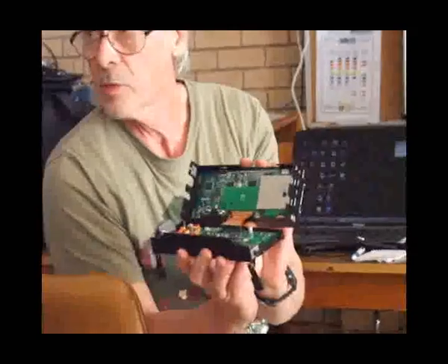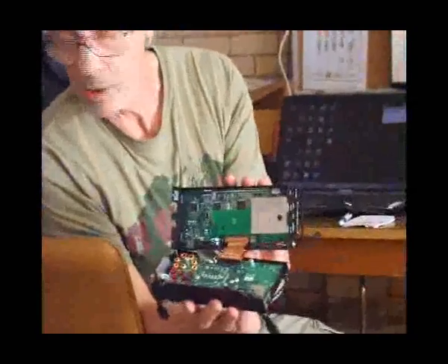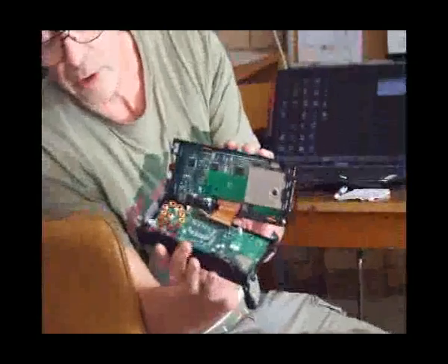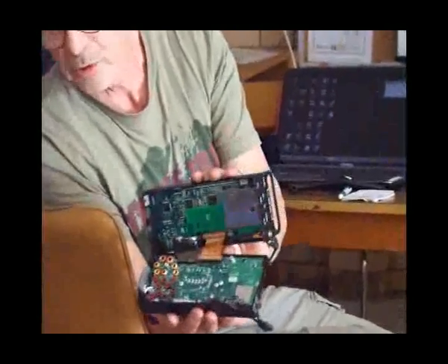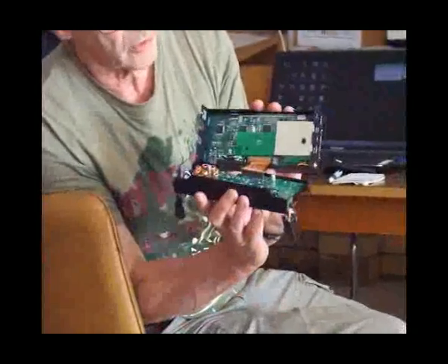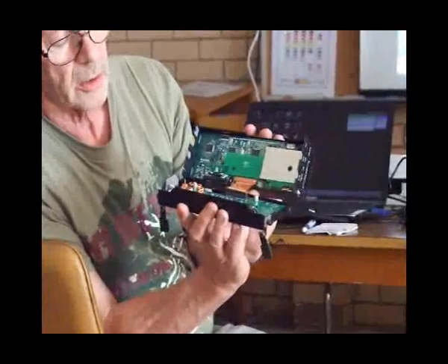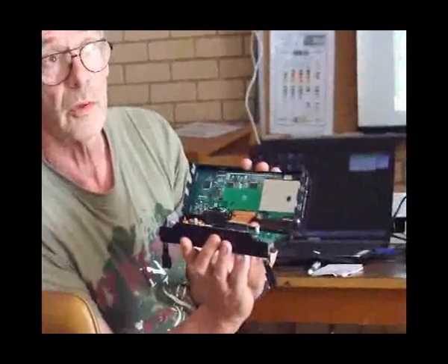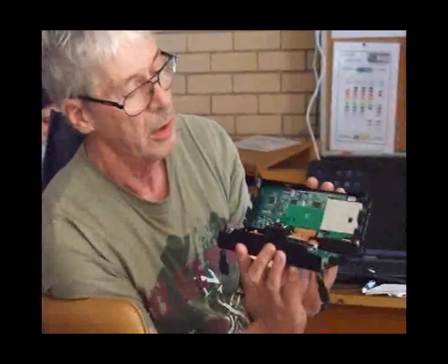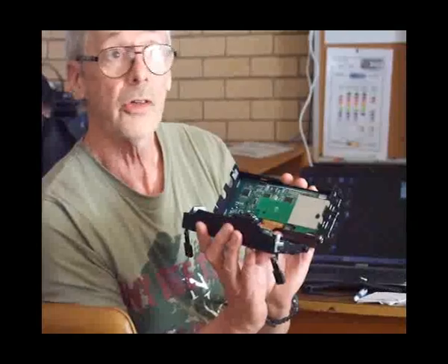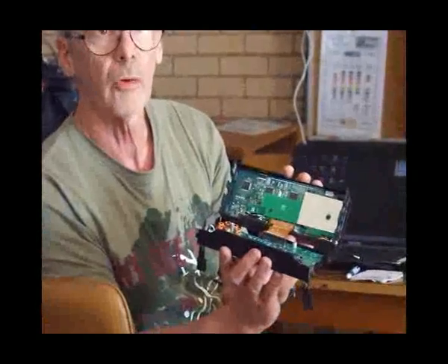You've only got two circuit boards, a control board, and the bottom one is the RF board that holds all the RF circuitry. You can see the bandpass filters there, and the amplifier is basically at the bottom, where I'm touching. You see the little RF output transformers, and they're just linked with a cable. To build it, the hard part is getting all the standoffs set in the right positions, and then you just install the circuit boards, put knobs on, connect wires up into the correct places, and the radio's built.